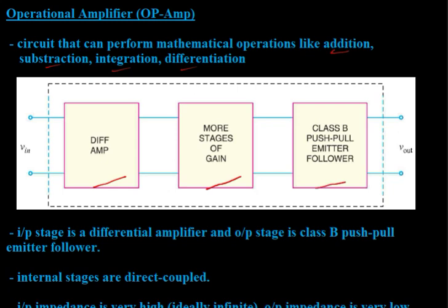The input stage is a differential amplifier, a particular type of amplifier which amplifies the difference in the input voltages applied to that circuit.